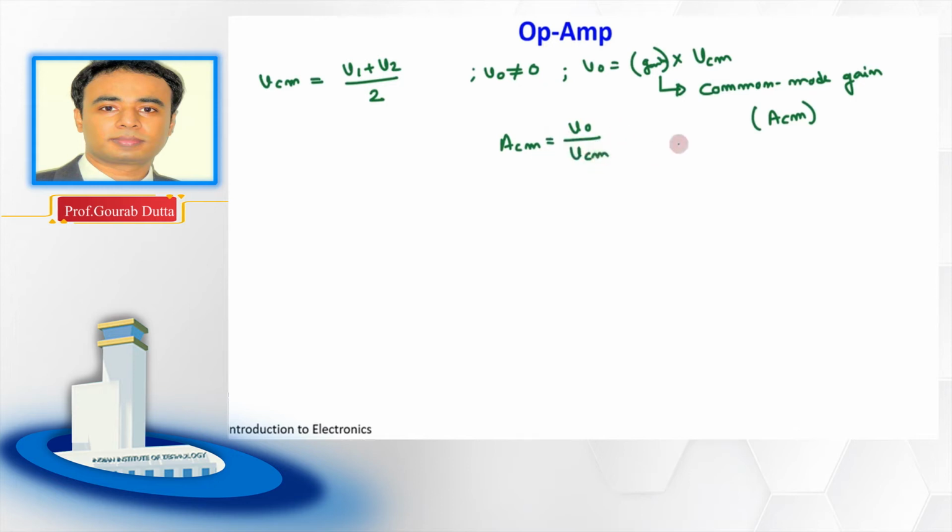So in this regard, regarding this common mode gain and differential mode gain, we want the op-amp in this difference amplifier to amplify only the difference, but we can see that in certain cases we do also have this common mode gain. In this context, one figure of merit has been introduced, and this particular figure of merit is known as common mode rejection ratio.